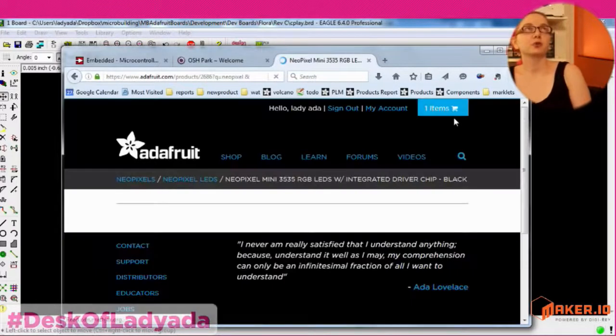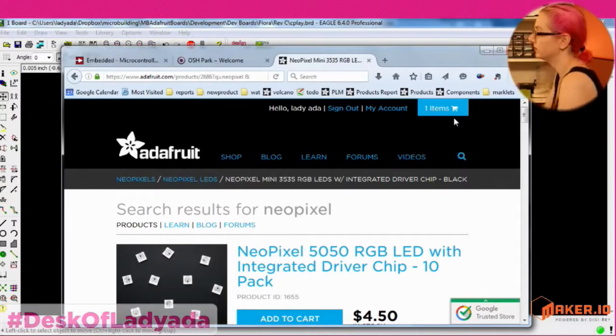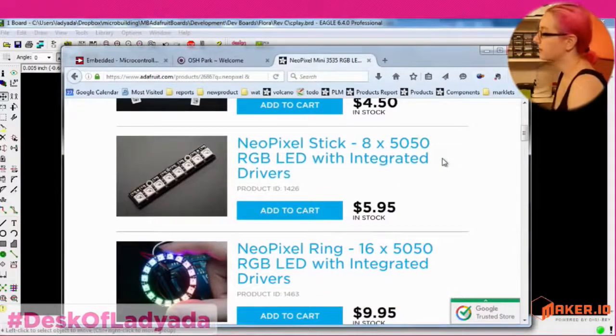Having manufactured with this component meant I knew that the yield was pretty good. Some LEDs can have iffy yield. Just be aware of that. If you have one component that has bad yield, especially LEDs, they sometimes crack during manufacturing if you don't desiccate them properly and dehumidify them. Just something to watch out for.